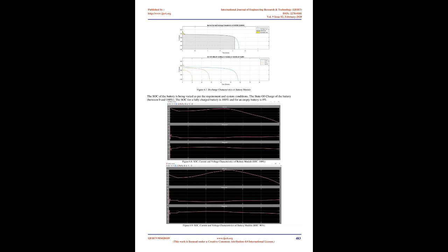1980 Hz, 33*60, 3-level 3-phase VSC. The VSC converts the 500 VDC to 260 VAC and keeps unity power factor. A 10 kVAR capacitor bank filters harmonics produced by the VSC. A 100 kVA 260V/25 kV 3-phase coupling transformer.